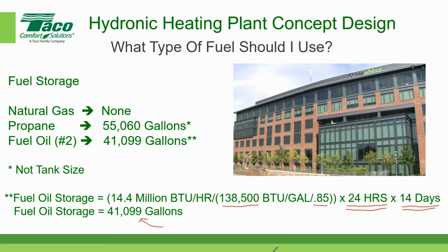So even in New England, during the design day, when the building is occupied and it has people, and equipment like computers and the lighting, there's a certain amount of internal heat gain. So the amount of heat loss that takes place is reduced, and also during the daylight, the temperatures are a little bit warmer, and you also get the sun effect.